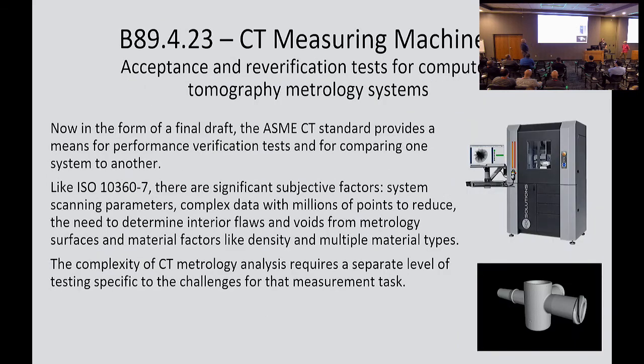Well, and so you can never get too much of a good thing again. And so there is a newly released CT standard from ASME. And it has artifacts and it has procedures, but the difficulty that comes in here now is that the subjectivity hits another level yet. So, gee, my vision system, well, what about magnification? What about lighting? What about edge finding?